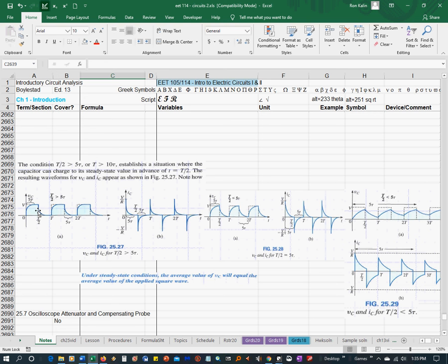And then whenever it discharges, this is the charging phase, this is the discharging phase, and so on. It keeps repeating. The current starts off high because the capacitor starts off as a short, trails down to 0 because it ends up being open, and then it goes in the negative direction, and it keeps doing that.